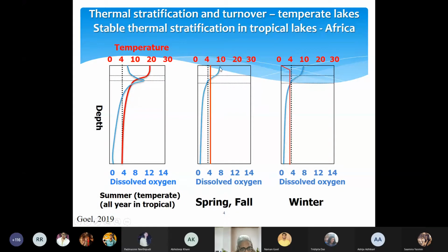because whatever is at the top is in response to the ambient temperature. That's why you can see the DO saturation is higher. This point has gone higher, and the temperature remains the same, but as you go deeper into the water column, the DO is being depleted by the bacteria and maybe even other higher organisms.